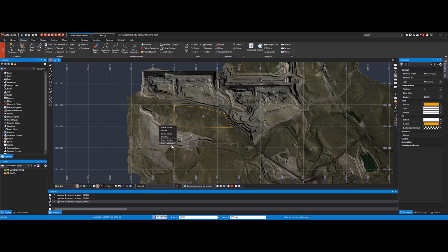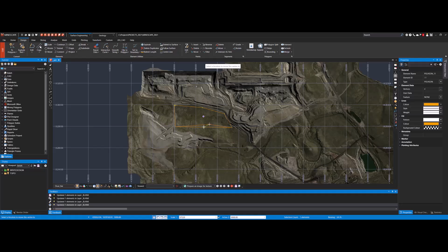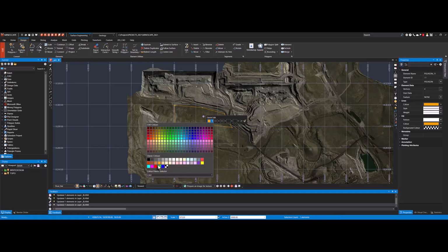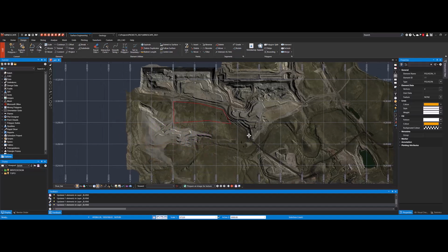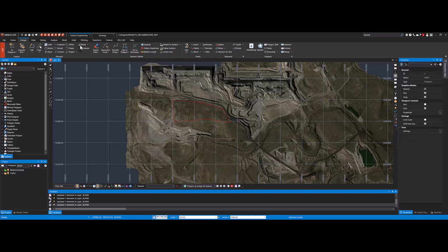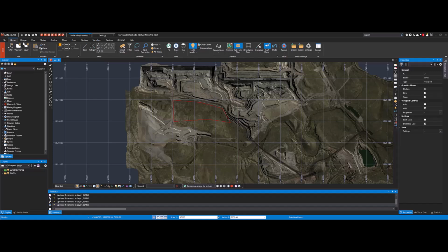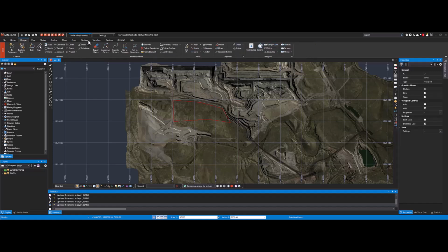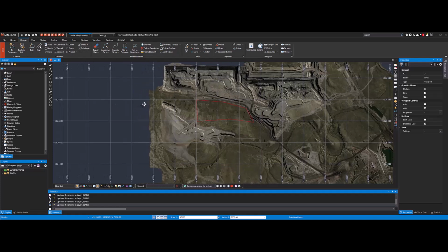If you want to create polygons or line strings for a lease limit or a pit outline, you can do that quickly and cleanly. This functionality is available at the mouse level, minimizing moving to and from the ribbon. It's all about being efficient. RapidCAD also gives me advanced geometry tools. For example, you can offset haul roads, create parallel alignments, or automatically clean up overlaps and intersections.